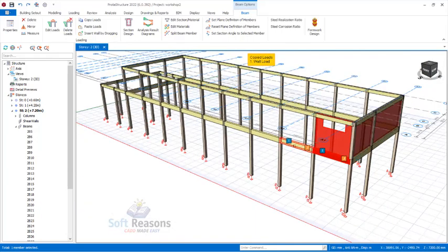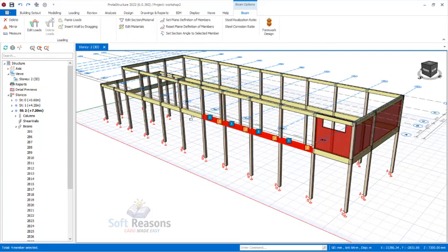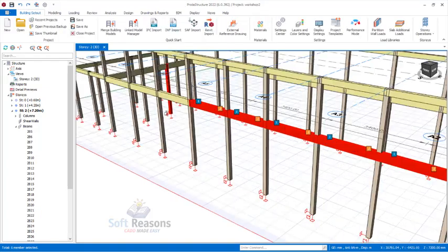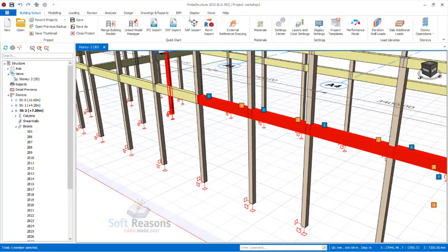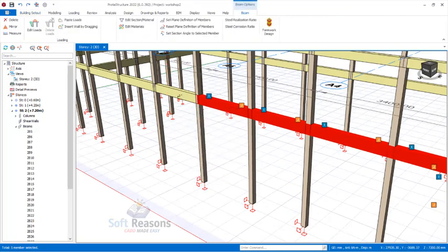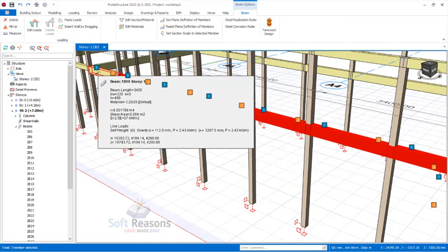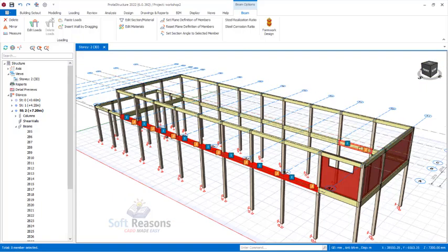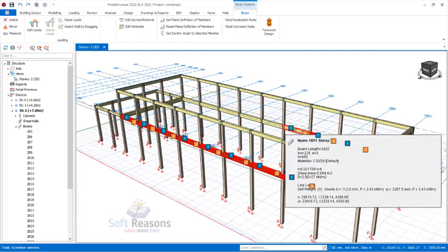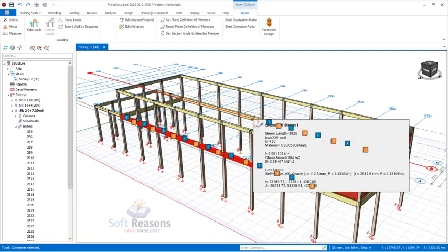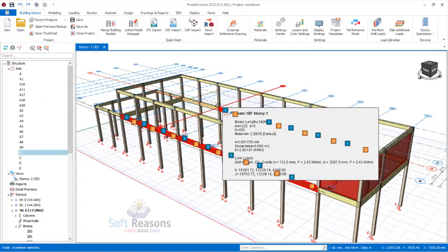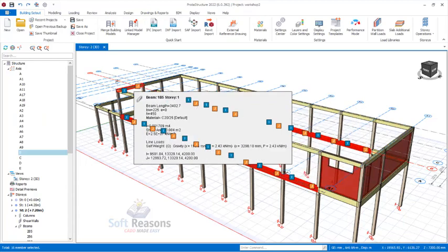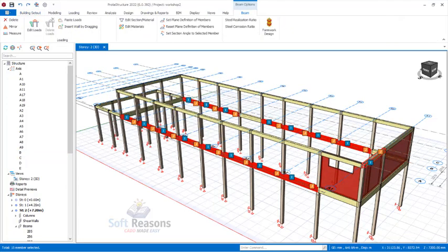We want to copy opening, so select the first beam with the control key, and then you can have multiple of these beams selected. You see, I mistakenly selected the column, so click on it to deselect it, beam and beam right there. So you can also come over to these other directions to select the beams right there, just like this, deselect these grid lines, and then select this beam.